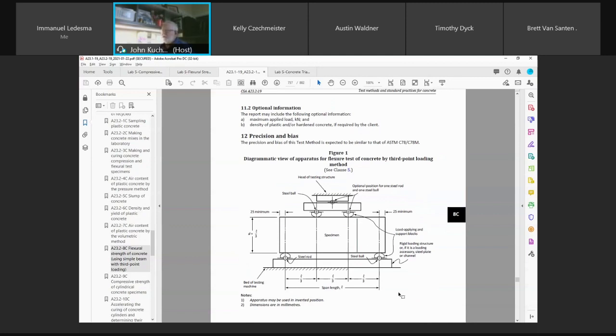And when these beams fracture, when they break, then you can physically measure with calipers from where it breaks to this line. So when we slide this in a machine, it's easy. We take a felt marker and we make a mark here, we make a mark here, and we make a mark here, and we make a mark here. Because then as we're watching the machine, as the test is being carried out, we'll see right away if it fractures, boom, right here, then we know, okay, we broke in the middle third. And sometimes it'll break nice, pretty vertical. Sometimes it may go something like this. I've had beams where it starts to fracture here in the middle third and then goes up to the outside. So we didn't go to that.